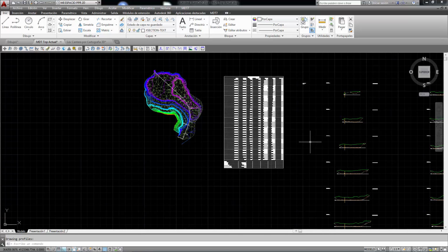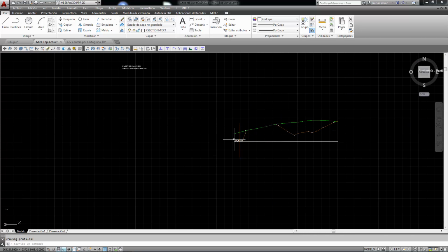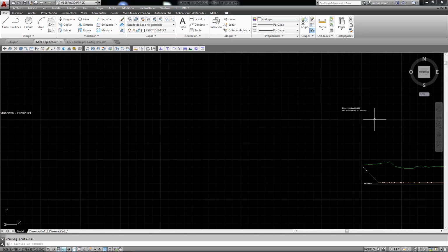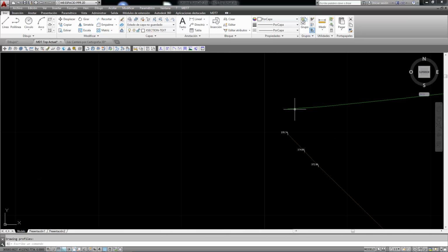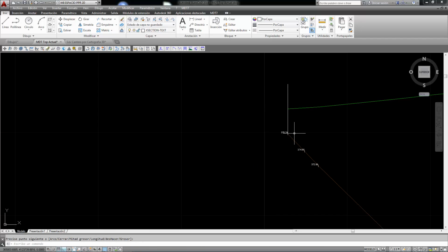Let us see what we were referring to in relation to calculating the vertical cuts or prolonging. In this case here, we have a cross-section that is shorter than another that does not cut. The program will calculate a straight cut by default, but we can also assign a specific inclination to the slope that also prolongs or cuts them.